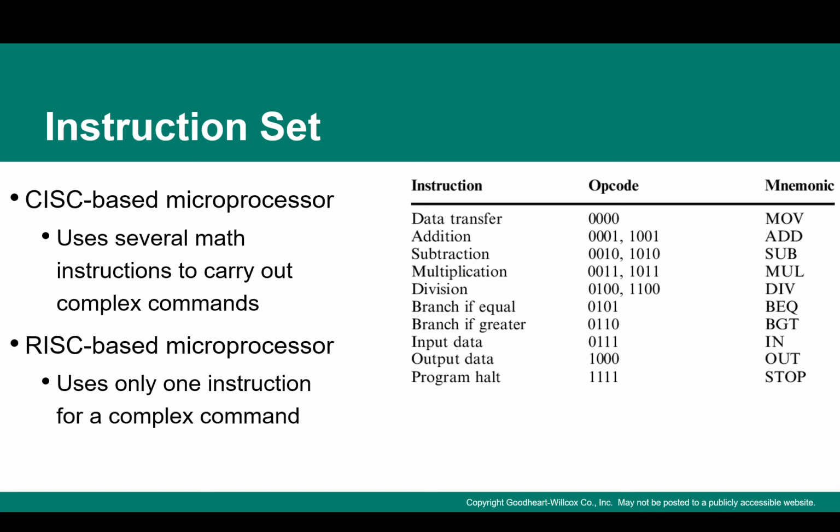And that's what the instruction set is. As I said, an MPU has a fixed number of instructions which it can understand. For example, here we want to transfer data, and here is a mnemonic. In assembly language you can use the instruction MOV. But whatever language you program in, whether C, C++, Python or any other, whatever line of code you write will get converted into an opcode.